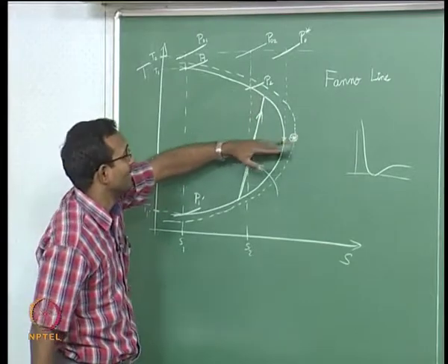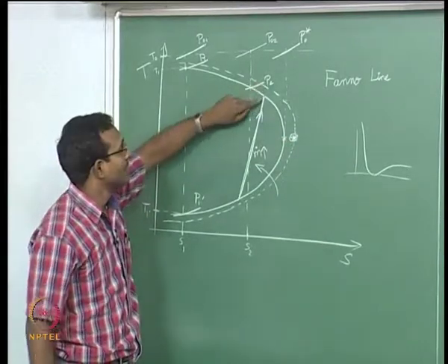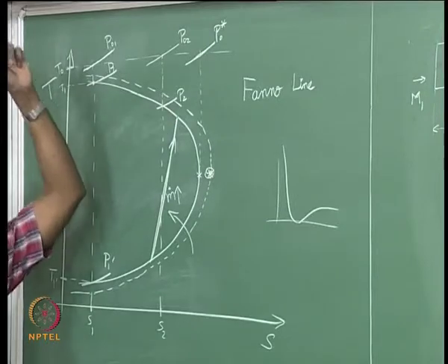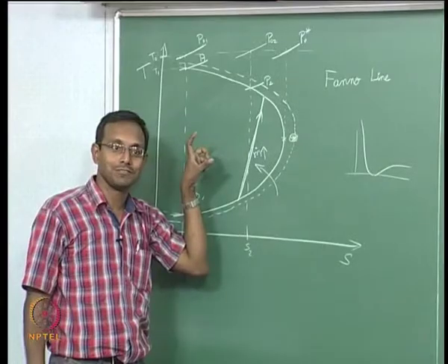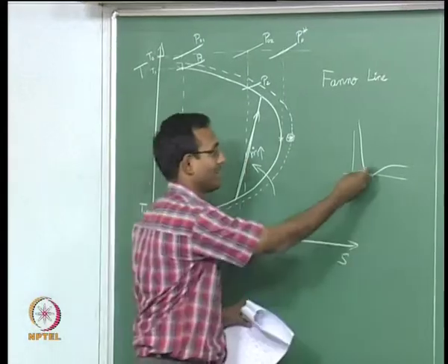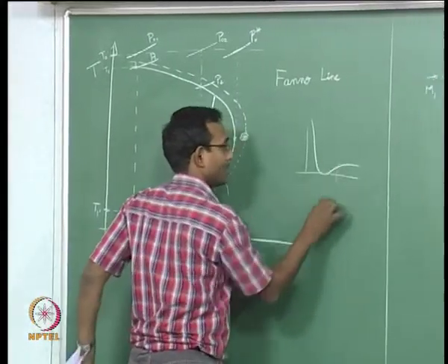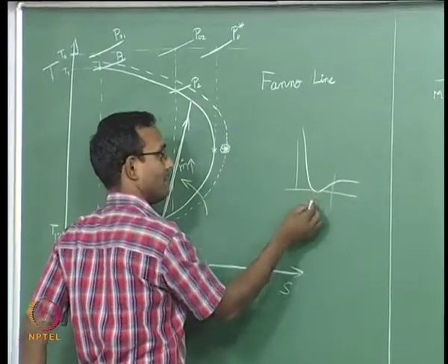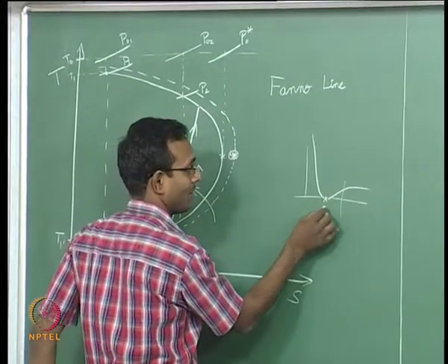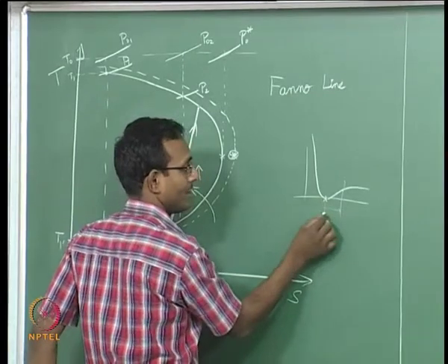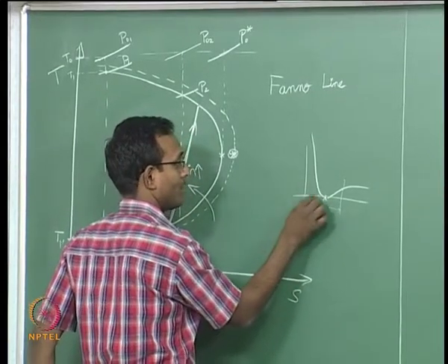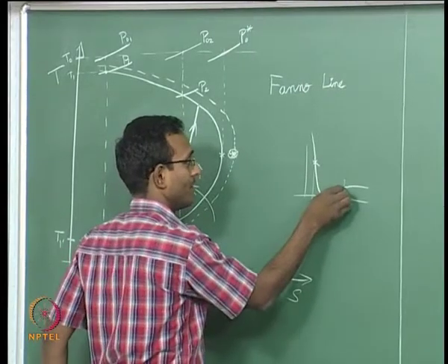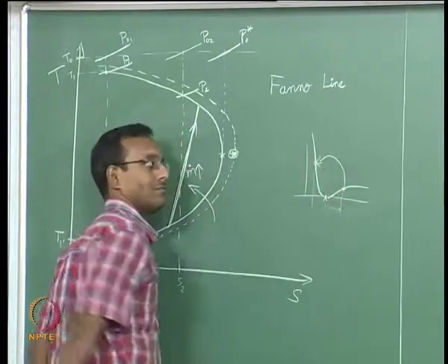We know that above this line it is a subsonic solution. And when it is a subsonic solution, suddenly my L star is very high for the same f and dh. I have this curve here. Say I chose this particular Mach number, and from here it jumped to some other very low Mach number. This is M equal to 1, this is my supersonic limit, so it is going to go very subsonic, somewhere sitting there. From here it chose to go there.